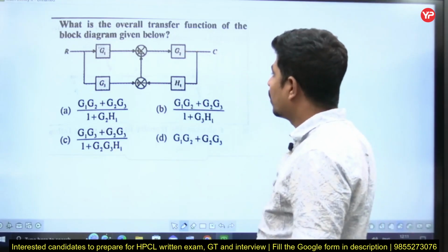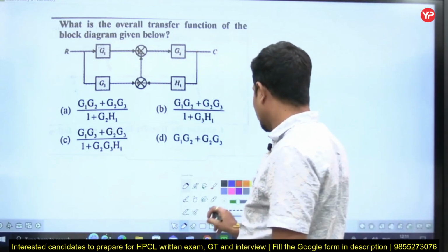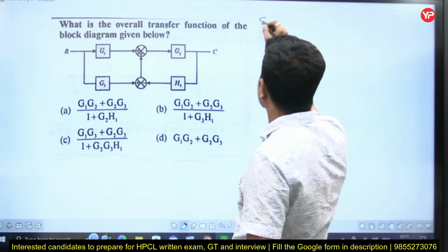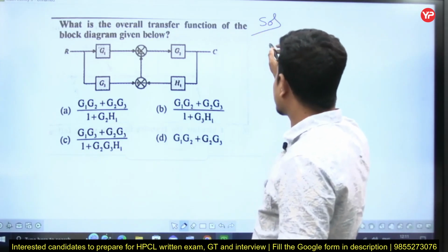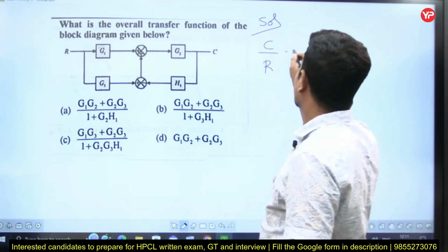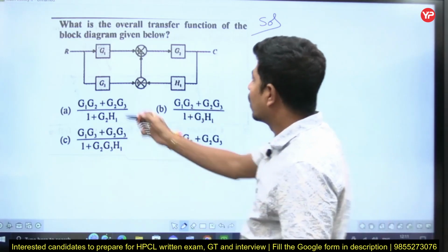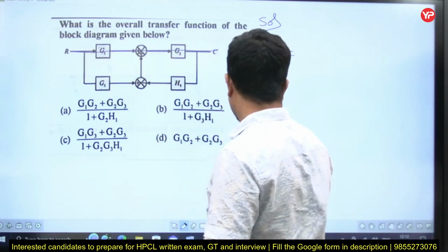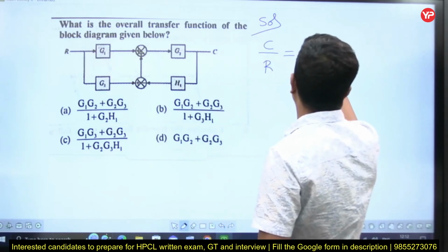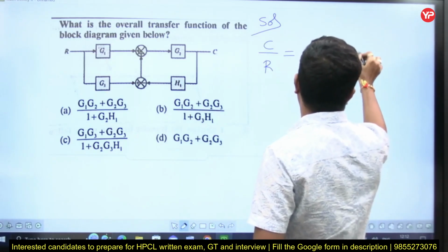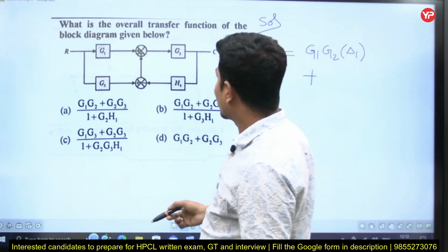This is one block diagram. He's asking what is the overall transfer function. Overall transfer function and transfer function both are the same. Now C by R is equal to... how many forward paths do we have? This is the first forward path. What is the forward path gain? G1 G2, into delta 1, plus...